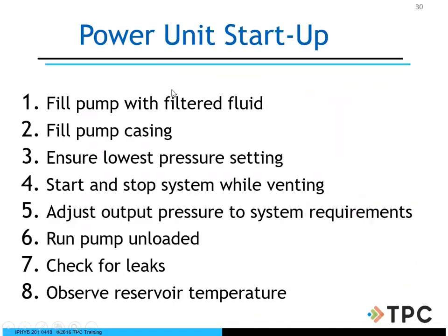On power unit startup, and this happens quite a bit, there's still pressure on the hydraulic power unit itself, so we want to fill the pump with filtered fluid to reduce or eliminate contamination. Fill the pump casing and ensure the lowest pressure setting, because if you have a high pressure setting and you turn that motor and pump, you already have pressure on there. You're going to stall out your motor, and that's what you don't want to happen. You can actually ruin your motor and pump as well.